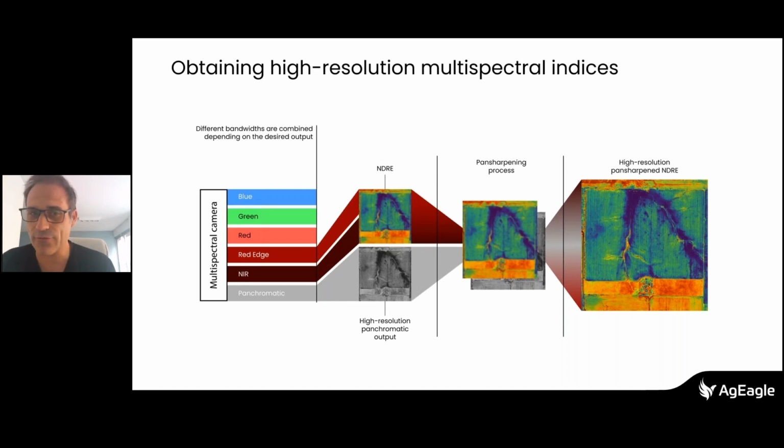So that's the way Pix4D and Metashape do it, actually. And there is a reason for that. The lower resolution multispectral imagery will process much faster. If we do the pansharpening first, prior to the stitching, we will need to work with many more gigabytes.